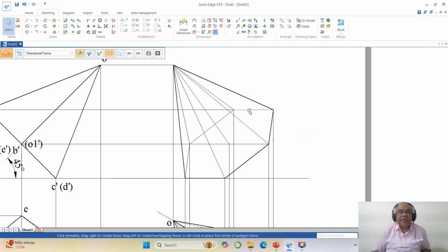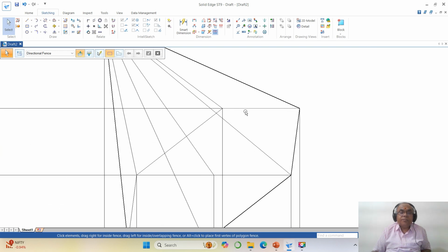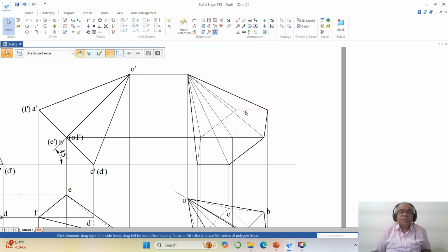Then we have the surface near to the observer that is visible. You make it 0.3. Fine. So once you do that, this is the one we are talking about. The entire base surface is near to the observer. You take this and make it 0.5. Now once you do that, from a point, if any one of the edges is visible, then automatically all other edges become visible.